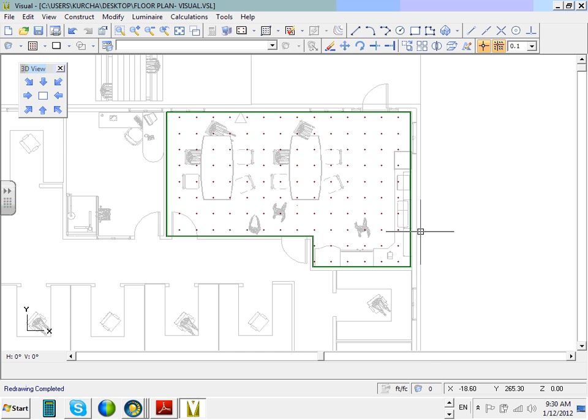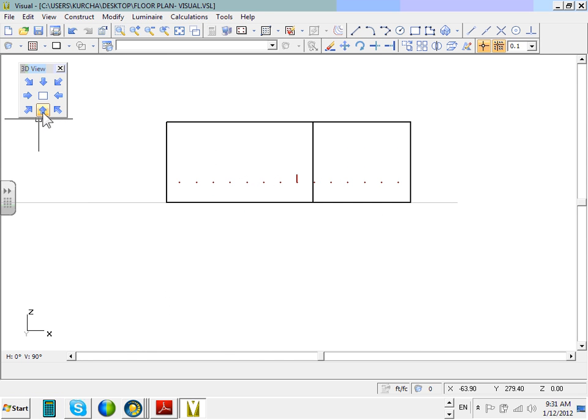If you look at the south view, which is the bottom, this is the ceiling, this is the floor, and this is the 2.5 line. If you don't see what I see, you did something wrong. So you can see where the calculation is going to happen, right at 2.5 above finished floor. Can I get thumbs up, thumbs down?